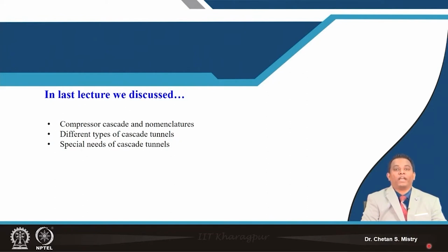We realized that our blades are made for particular angles which have already been calculated. Because of my inflow condition, the flow may not be incident at the design angle, and may strike the blade leading edge at another angle, and that is what we defined as the incidence angle.